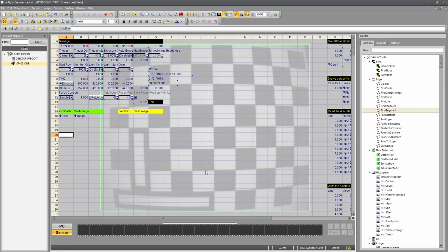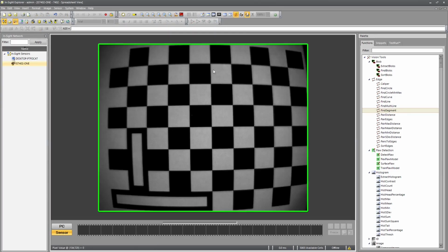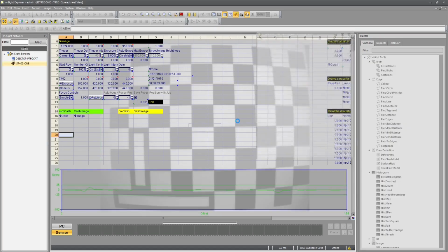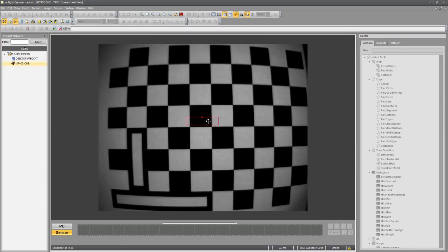And now you need to be careful which one you're using. One way for us to verify that our calibration worked is to use the fact that each of these squares we know has been printed to basically exactly 20 millimeters in dimension. To identify that in the image, we can use the find segment function. If we select a region that contains exactly one segment, which is a point at which the contrast has changed and then it's changing again after some distance, so going from a white to black transition to a black to white transition means that there is a black segment in this region.